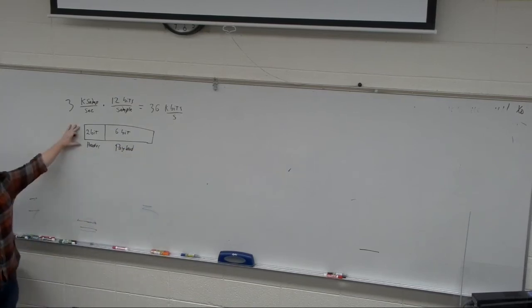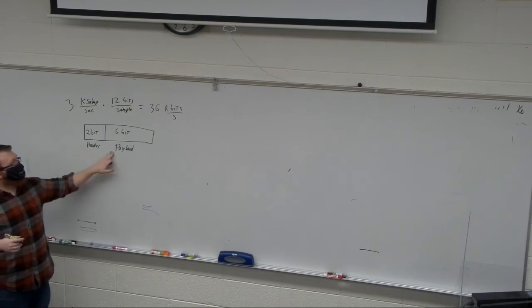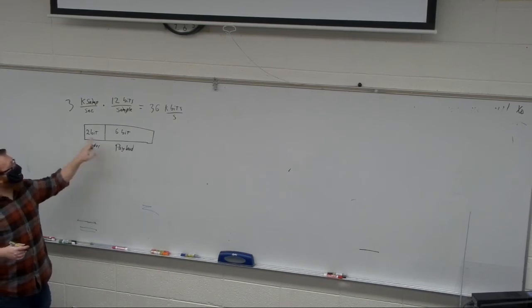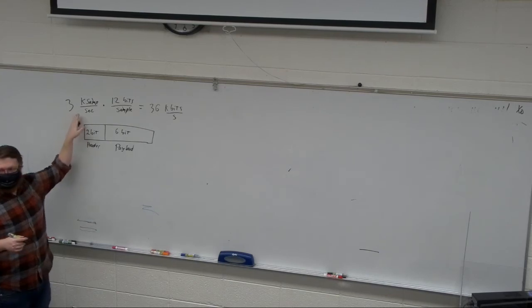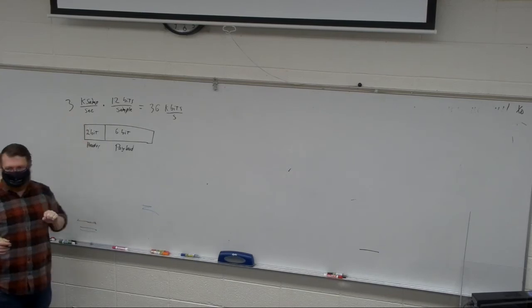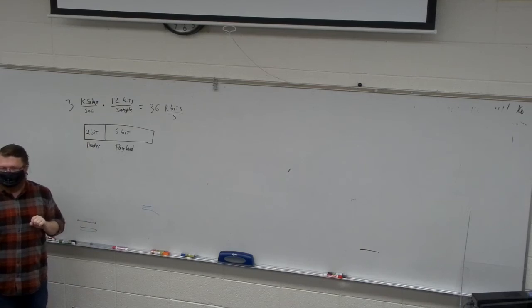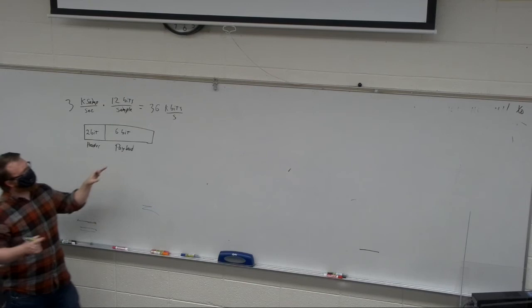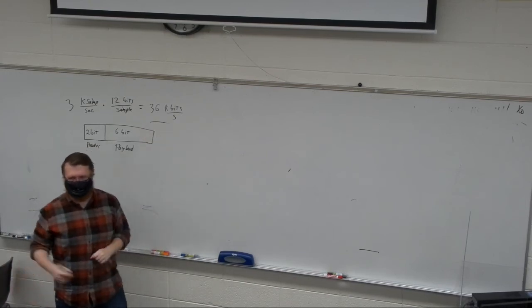We don't have a lot to do with this header just yet, but you could picture how this gets easy. You could contain which channel the data is coming from, or what it is sending you, right? We might have an ADC input and we might have a user interface or something on the FPGA. That's where we use headers, and then the payload. So really, for every ADC sample, we need 2 UART packets. So we're essentially doubling that rate with overhead.